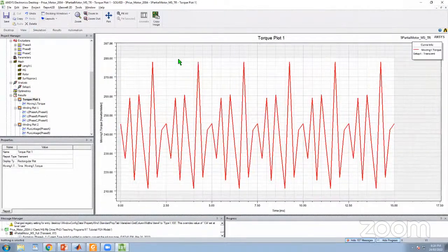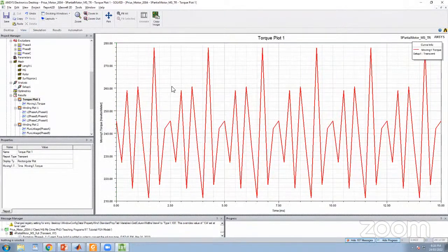Then the first very important performance parameter we can get for the motor is the torque. We get that when the motor operates at 3000 RPM, when we supply the maximum current to it, it can generate a torque of around 240 Newton meter.